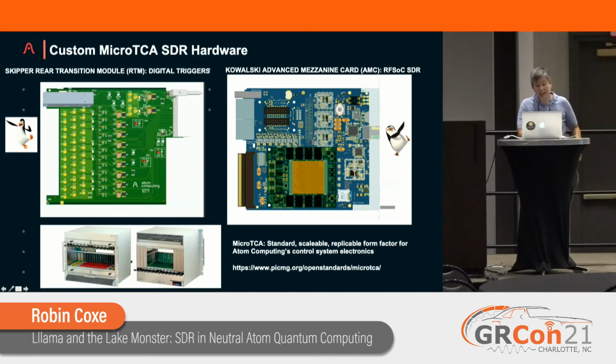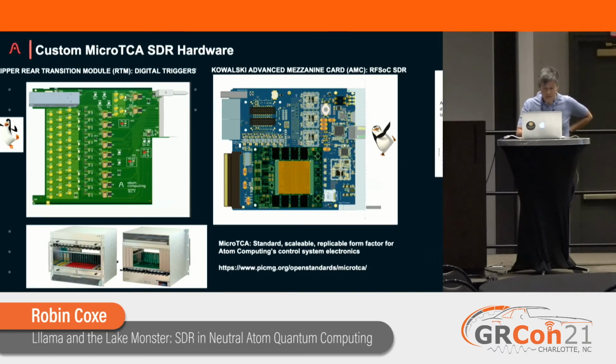So this is our SDR card. We actually are using our RFSoC system on module because it made the design a lot simpler. And then the way the MicroTCA chassis is constructed, we can have mezzanine cards coming out the back. So this is our digital trigger board coming out the back. I like penguins, so these are named after 2 of the penguins of Madagascar. And this board actually exists, and this board is getting assembled right now.